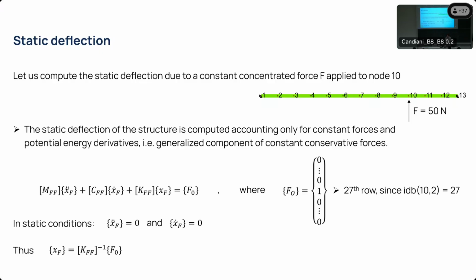To do that, we can use a small trick. We have a lot of tricks using finite element analysis, which is the fact that a constant load will result in a constant displacement. The load is not changing, so after settling in, the response of the structure will be constant. I have never seen a bridge moving due to gravity waves.